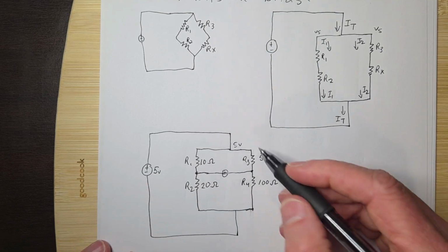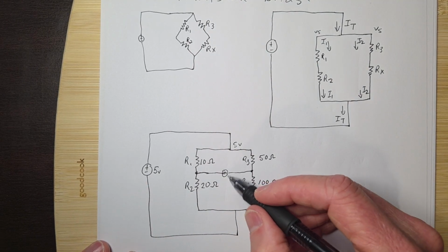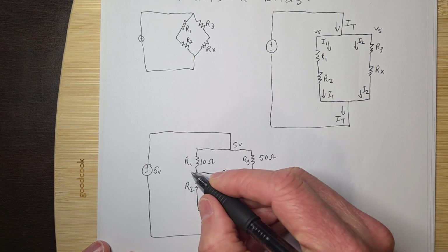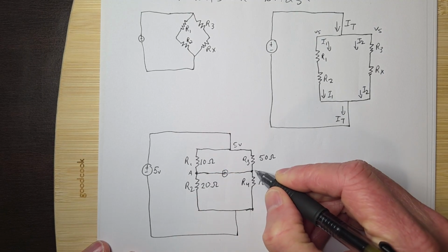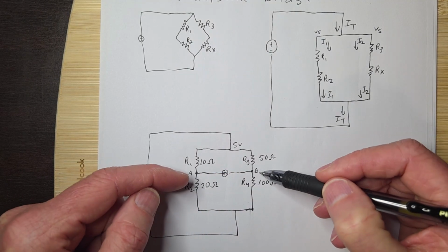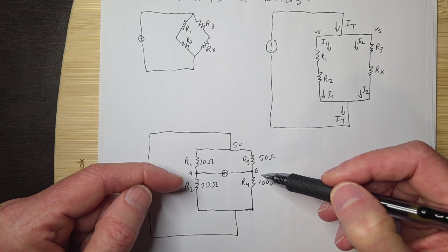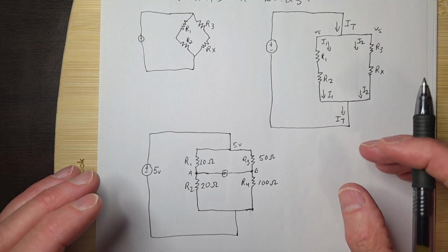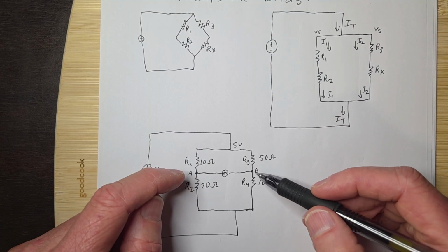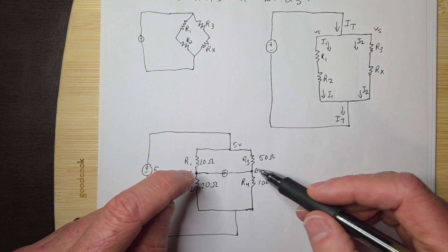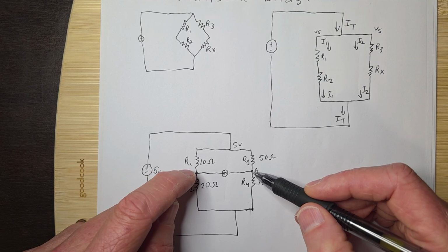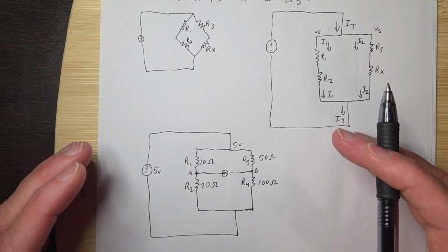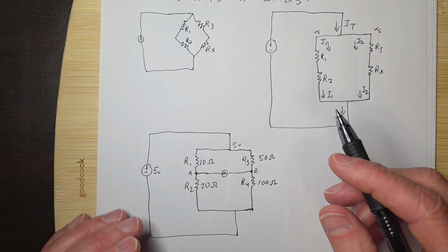And when the voltage is 0 volts, in other words, when there's no difference in potential, when A and B, we'll call this node A and this node right here B, are the same voltage, there's no potential. And if there's no potential difference, then current can't flow. So if this was 3 volts or 3.33 volts or whatever it's going to be right here, and this is the same, then no current can flow. You have to have a difference in voltage for current to flow.